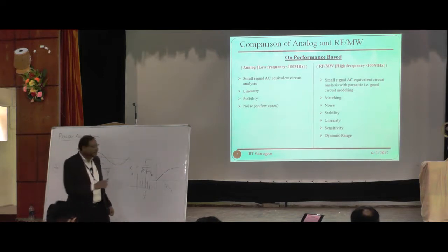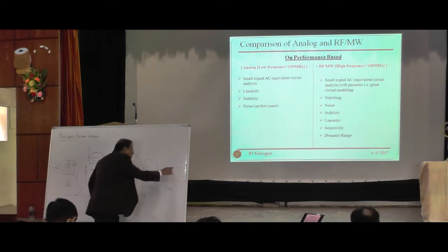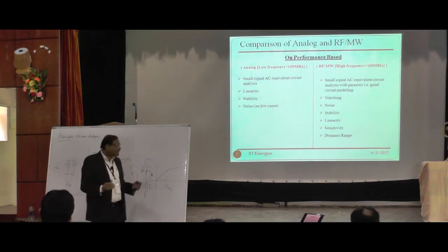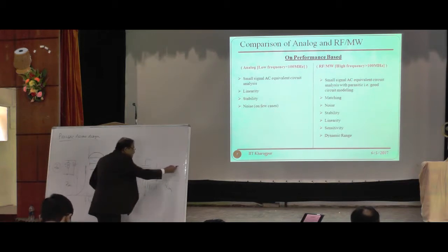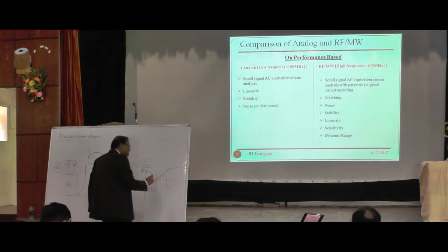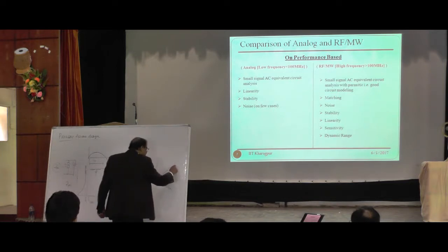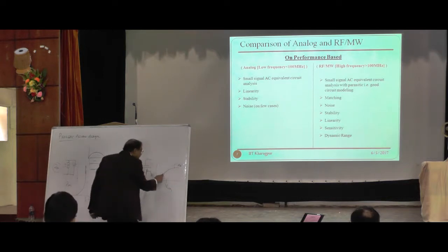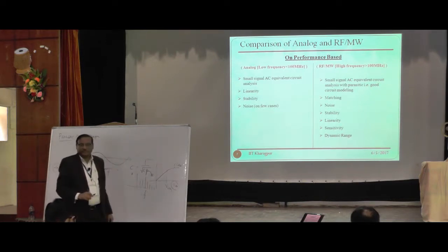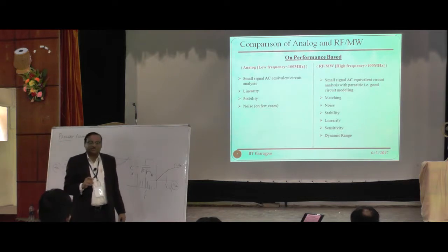That is the nonlinear part; this is the linear region. Here harmonics are created and energy gets distributed among other harmonics. We define the input level at which there is a compression of the expected linear output as the 1 dB compression point. So that is the linearity of the system.